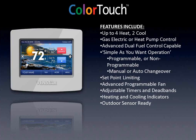So you could say Monday through Friday, say it's a commercial building, I want to run the fan from 8 a.m. to 5 p.m., and on weekends I want it just to be a regular auto fan. You can do that. Or you could even say, from 8 a.m. to 5 p.m., I want the fan to run for the first 15 minutes of each hour, and then I want it to be off for the next 45, unless I happen to have a heating or cooling call. So that'll take the place residentially of some of those fan cycler controls that you guys have been required to put on by code to either turn on the fan or turn on the fan and open an outdoor air louver. This stat will be able to do that for you without any additional fan cycler controls needed.